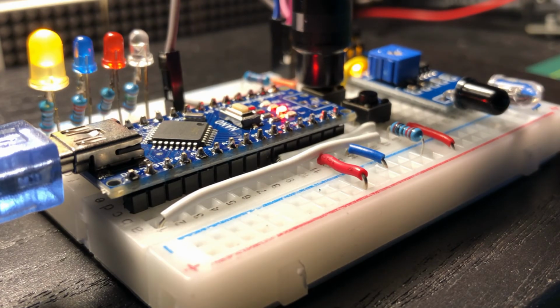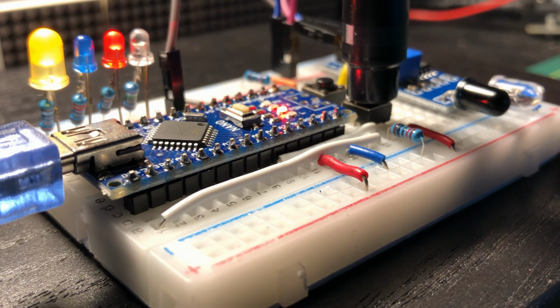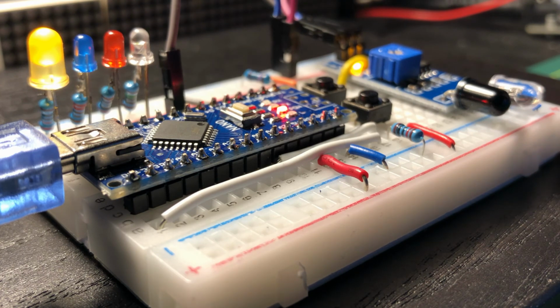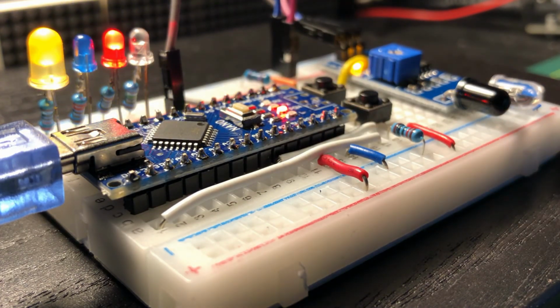The normal execution of the program is blinking of the green LED. When switch 1 is pressed, interrupt 5 at pin D13 occurs, causing the blue LED to briefly blink. Pressing switch 2 triggers interrupt 13 at pin A5, causing the red LED to blink. When the IR sensor is triggered, interrupt 20 at pin D4 occurs, causing the white LED to blink. If all 3 interrupts are triggered, interrupts will be executed on a first-come, first-served basis.